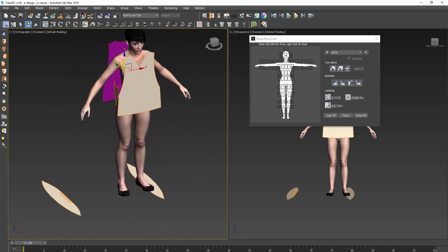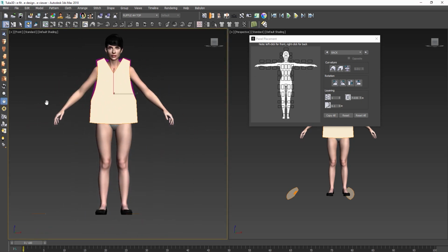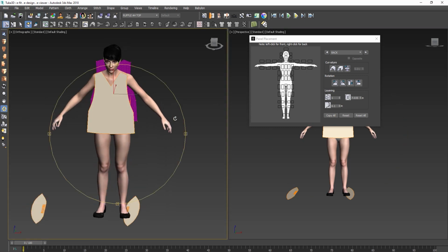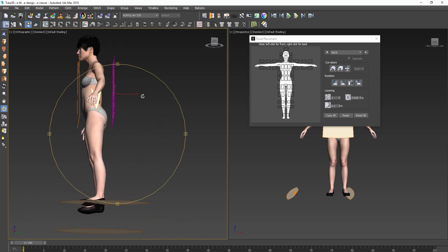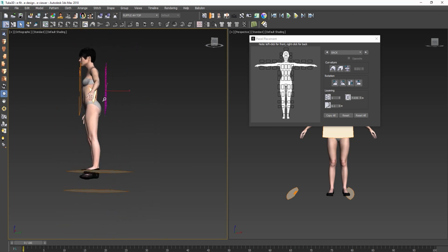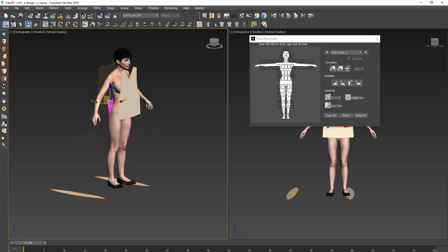Those two tools are also here, but usually I don't use them because I basically use my mouse, and that's enough. But there are some tools right here. The pen tool works the same as pushing down your mouse wheel, and the rotate tool is the same as holding Alt and using the mouse. Zoom in, zoom out is the same, just instead of using your wheel, you use this tool. But I just use my mouse wheel. That would be much quicker, I think.